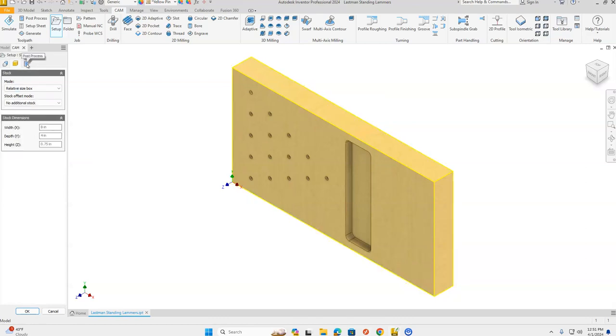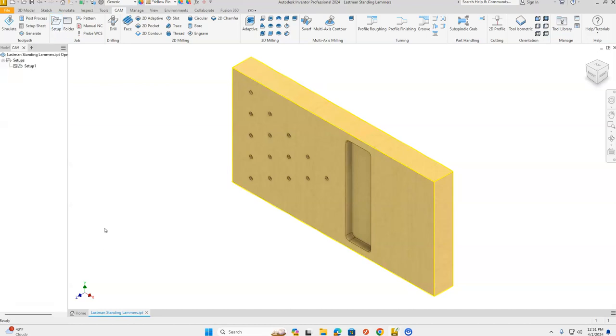Going on to our third tab, which is our post-process tab. When we select it, we're going to change the 1001, highlight that, and you're going to call this last man standing and your last name. And then down in the bottom in our model browser bar, we're going to click OK.